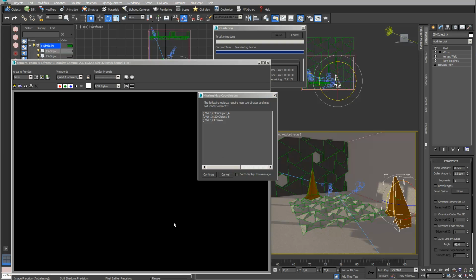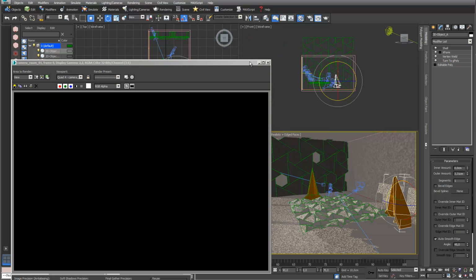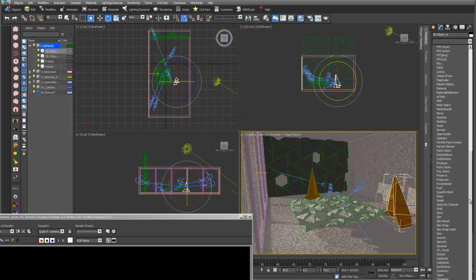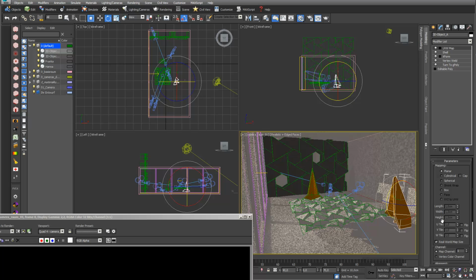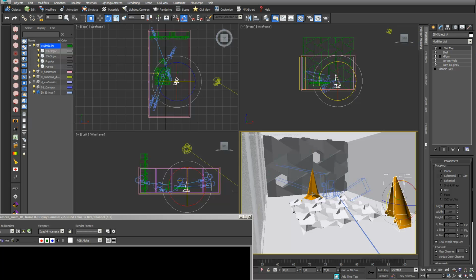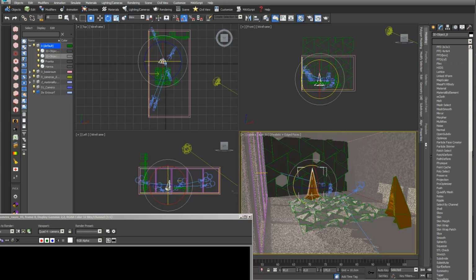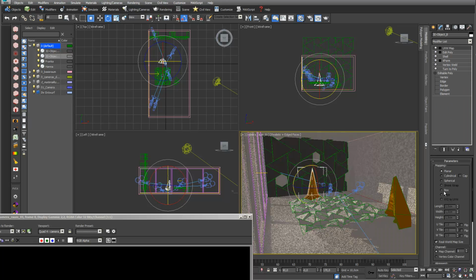It asked me, 3D Studio, that all my objects need a UVW map, so that my materials fit a little bit better. So let's see what I can do. I can just choose my objects, this one, and I add a UVW map, and I always use this box mode. And this one too, I add a UVW map, and I also use my box mode.